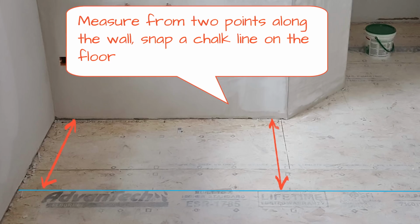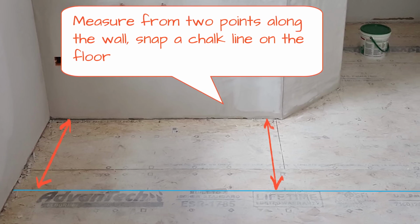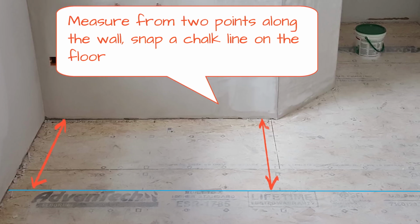So to create your first reference line, you want to find the longest wall in the room, and you're going to measure a certain distance away from that wall. It doesn't matter exactly what the distance is. This has no relationship to the tile layout or anything like that. All we're trying to do is establish a reference line that is roughly parallel to this long wall.